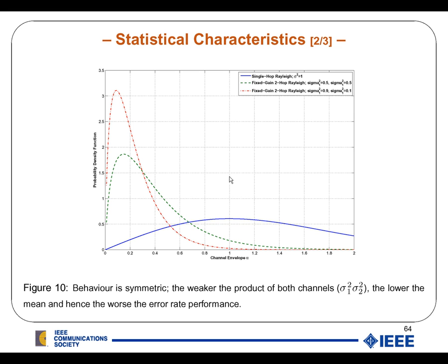Now we observe something quite interesting, and that is that there's a higher probability that amplitudes of lower values are realized. That means whilst we had the maximum for the relay channel here in terms of PDF, so a large likelihood that my channel will be realized is here, that is now shifted to lower values, causing exactly the deep fades which I referred to before. So we bear in mind that transparent relaying will cause deeper fades, which is given in these PDFs here.